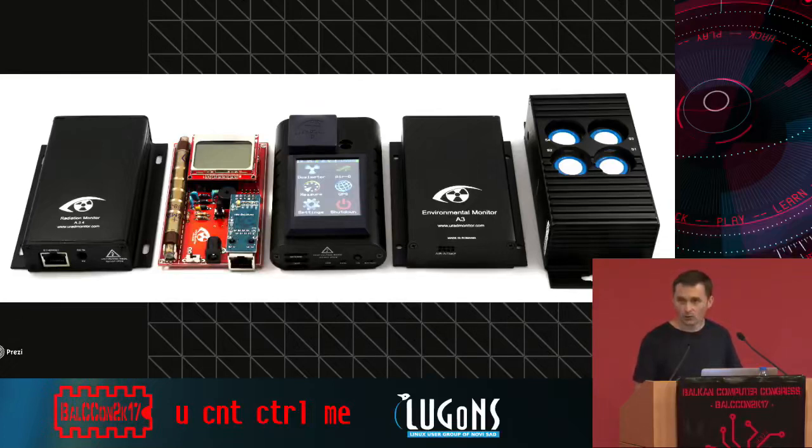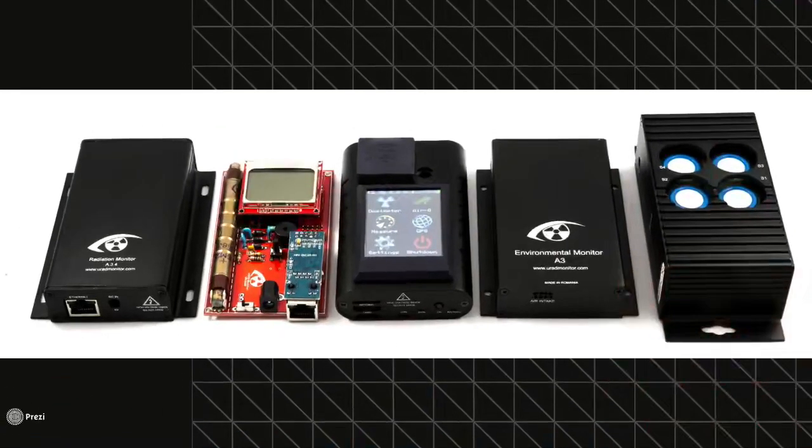It was interesting to go from one to another from a production point of view, like seeing how you can optimize the production of your PCBs, how you can do an enclosure, how you can test for IP protection, then to go to certifications like CE, what kind of tests are required there, what you need to check to improve in order to have the test accepted. Because it's not exactly cheap to do such a test, and in case the iteration you are trying to push fails, you will need to adapt and submit it again. It will be cheaper, but still there's money going out the window.